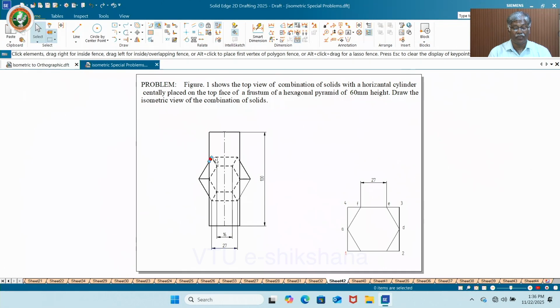We have in top view a hexagon of base side and then top face side. If you place the cylinder on it, definitely you cannot see whatever is below the cylinder, since it is top view. Now if you want, you can have a separate hexagon to draw the base and then scale it and then create this one.